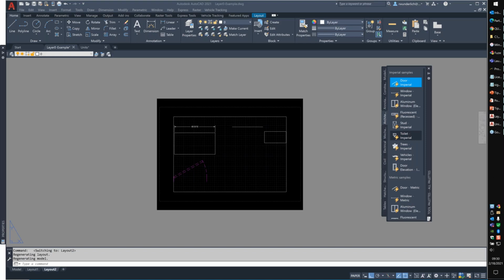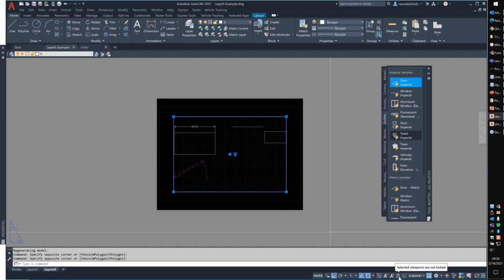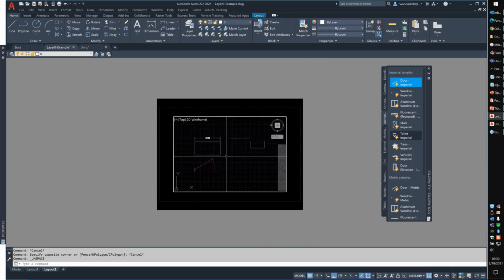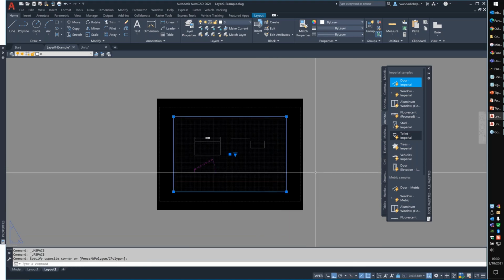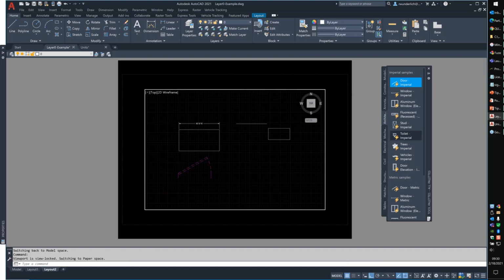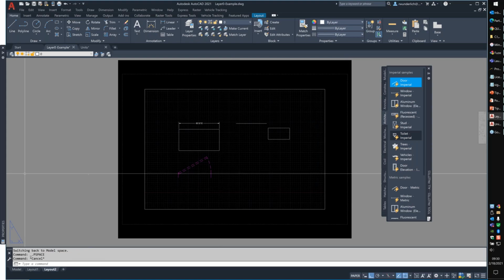In one of my previous ones, Joel, just so you know, I've covered locking viewports. You select your viewport, and you want to lock this once you've set your scale, because if I'm in unlocked mode, I can zoom in and out here by accident. If I lock this by clicking the padlock here, now when I make model space active, it doesn't zoom in and out the whole way. I did cover that in a previous one, but I will just cover that briefly here.